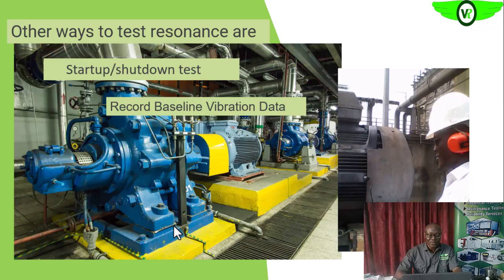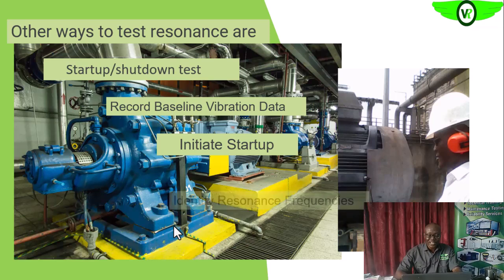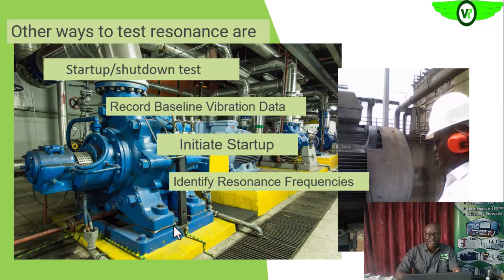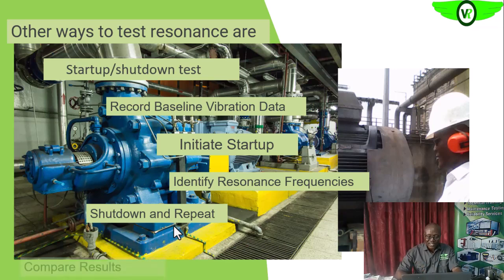From that test, you record your baseline vibration information during your initial startup. Then, as the equipment is going through the startup phase, you should be able to identify the resonance frequency. Then you shut down, and as it's coasting down, you also collect vibration information to be analyzed later. Then you repeat the process again to see if those significant events repeat themselves at the same time.